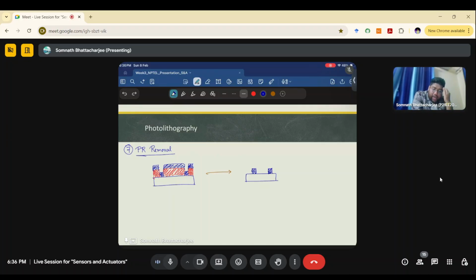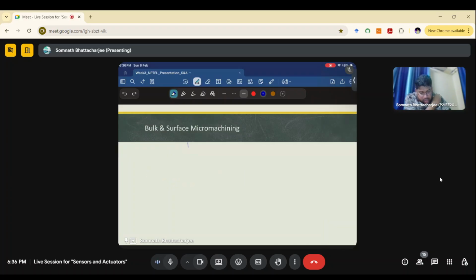So as we know, there are several patterning techniques: we can use a shadow mask, we can use photolithography and these things. But for ALD patterning, let's say we have a structure like this. This is the top view of the structure. Now we need to make something like this, and on top of that, up until here, you need to deposit hafnium or Al2O3 or something like that, and the rest part is as previous. So if this is your structure and you need to deposit up to here.